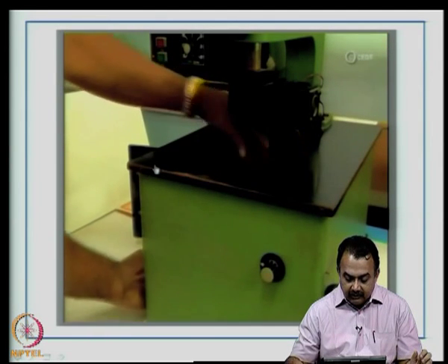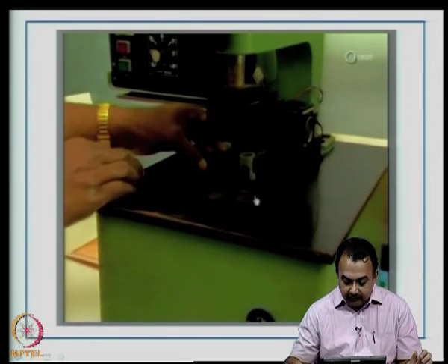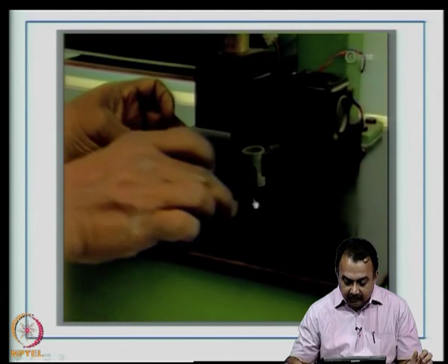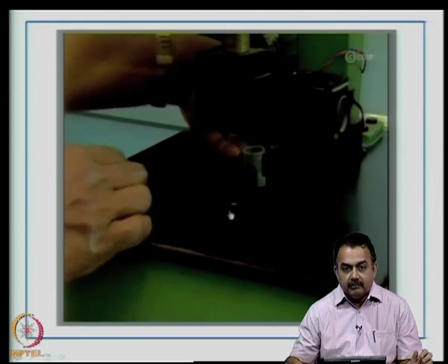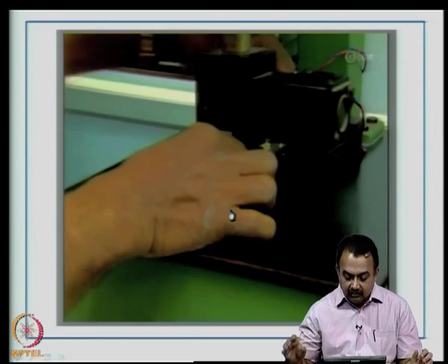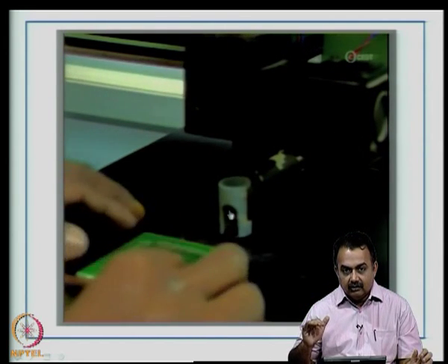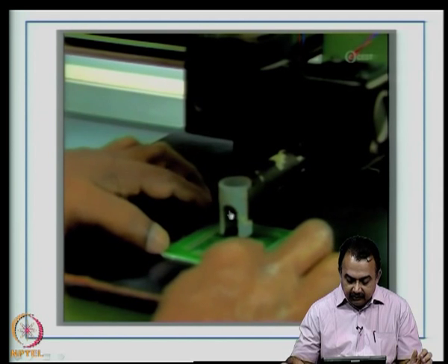Here again we are using tungsten carbide, and as you can see here, the drill bit is protruding. This height is very important because that defines the PCB board thickness for a complete through and through drilling. It can't be a through hole that is partially drilled through the depth of the laminate.